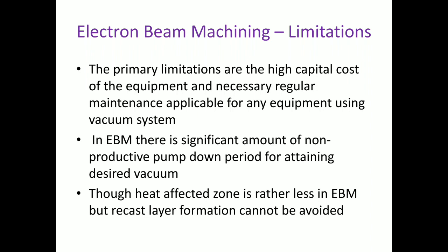In EBM there is a significant amount of non-productive pump down time for attaining the desired vacuum. What does non-productive pump down mean? Some time is required to pump out the air from the chamber and create the vacuum. So this is non-productive time which occurs in the EBM process, making this process a bit more lengthy than its usual time.